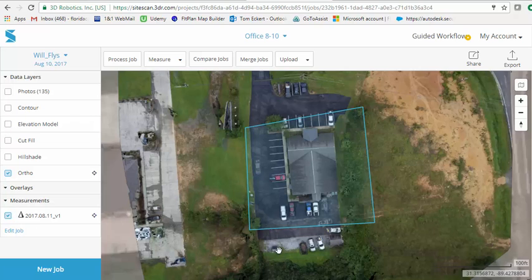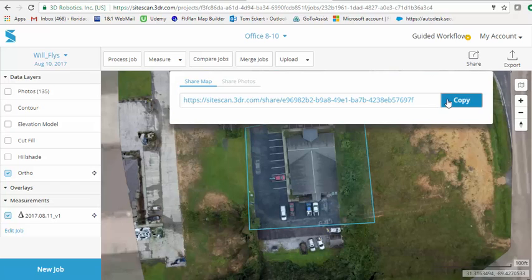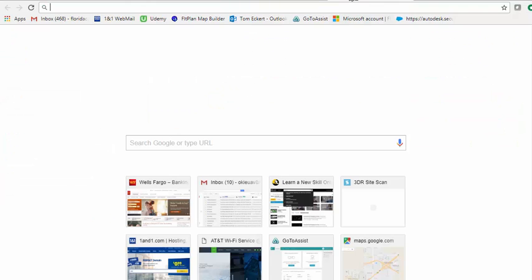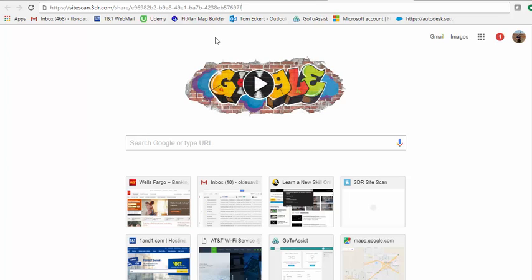Once we made our volume measurement, we've got it there. Remember, this share is amazing, whether it's a hillshade model, however you're copying it over, when you bring this in here, grab a new tab. I'm going to do a Control-V paste on the side scan, and I am sending out that orthomosaic with my volumes.